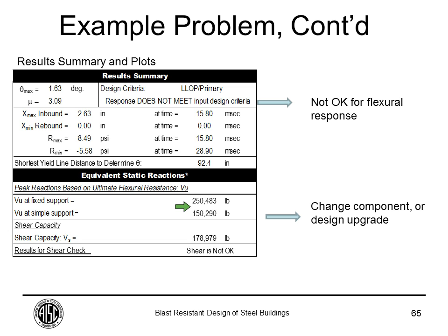So in this case, if it was an existing building, you would recommend that we need to add a web plate or something to increase the shear, or if it's a new design, you may actually end up changing the component.